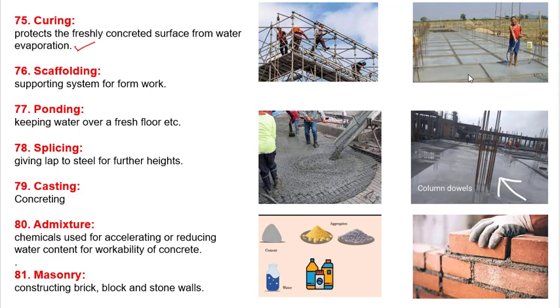So we need to keep the water inside the concrete from coming out. In this image you can see one type of curing. We call it ponding. He made different ponds and then placed water in each pond. So this is what we call curing.